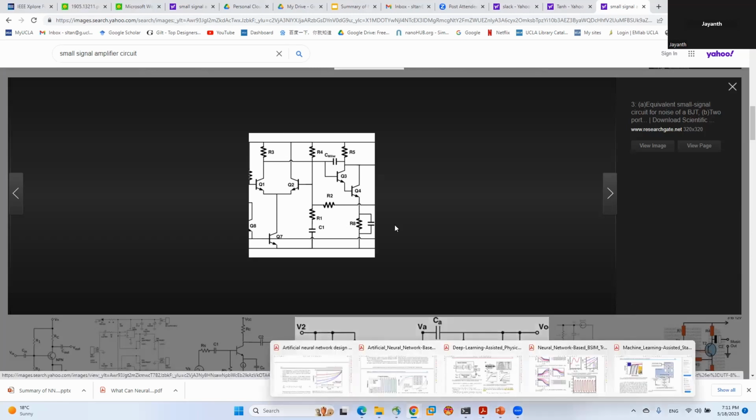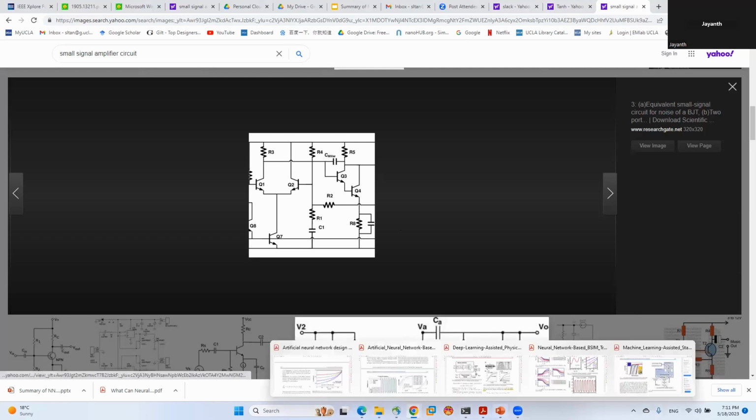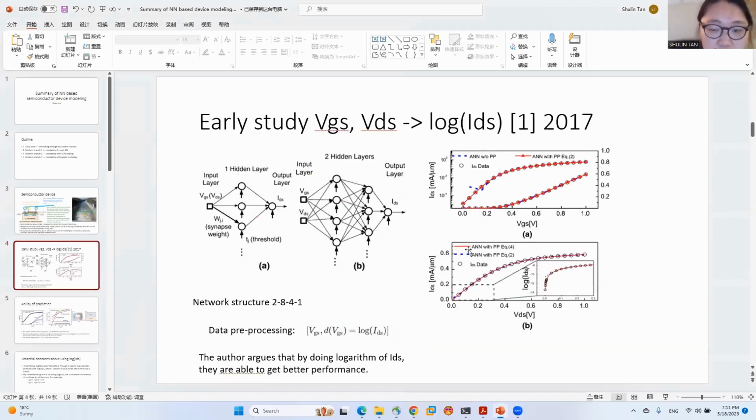And the other question I have is, the curves that you showed, of the current, has that been modeled mathematically as a function of VGS and VDS? It can be modeled mathematically, but your mathematical model will usually produce something that is kind of like fitting the reality, but it has deviations. It's very hard to produce a model mathematically to predict every condition in your device.